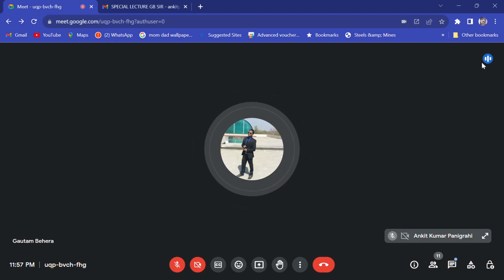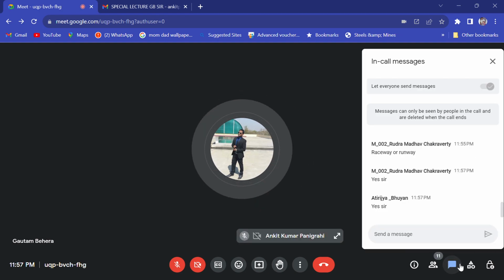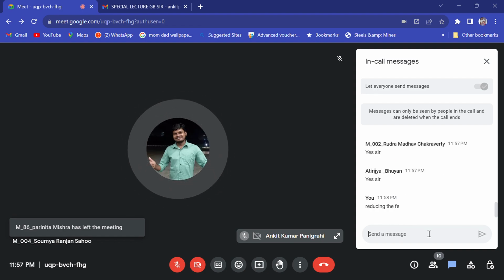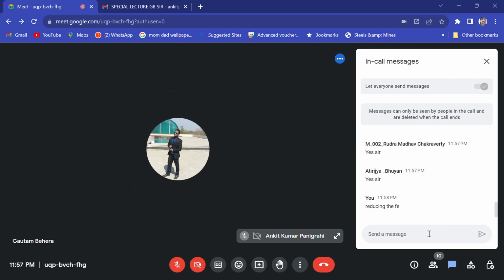Acha, can you remember what is the function of coke inside the blast furnace? Can you tell me? What are the main functions of coke in the blast furnace? Just tell me three important functions. Sir, coke supports the burden material. Very good. That is one of the most important properties. Anything else? It acts as a fuel. It will burn and release heat energy. You need heat energy for smelting, right? And it acts as a reducing agent. It will directly react with iron ore to give you iron, or it may react with carbon to form carbon monoxide, right? So coke will be used as a fuel, coke will be used as a reductant, and coke will hold the burden materials. It will sustain the burden, right?